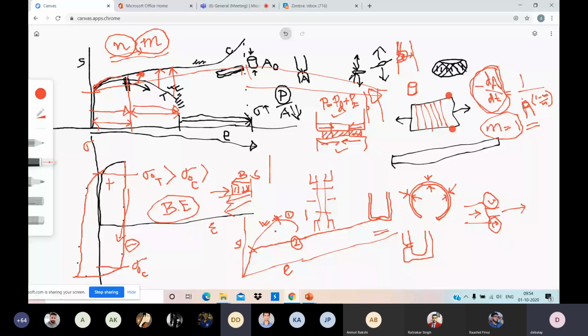So that we have some deformation zone. Yes, that is the right answer. When I do mechanical working, permanent shape change, on which region can I do it? I have to cross yield, but I should not cross UTS, because crossing UTS means necking. So this is my beneficial zone in which I can do mechanical working. If I apply a stress here, I get some more deformation, but I am not at risk of causing necking. And as it goes very close, I will stop my process. You understand?